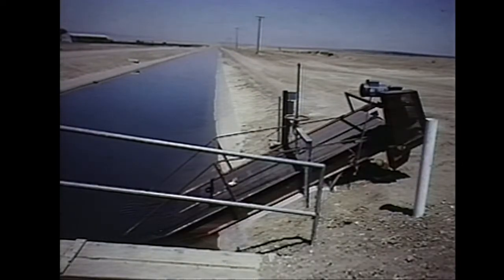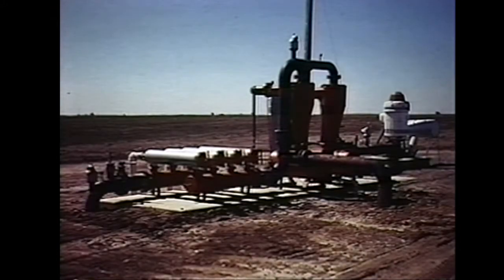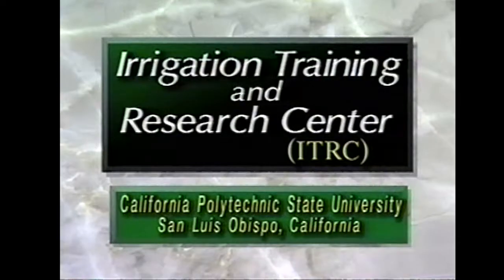In summary, there is a wide variety of filter designs available. Most filters are designed for a limited application. Others, such as media tanks, can provide filtration for a wide range of conditions, but only if they are sized, adjusted, and maintained properly. For more detailed information, the Cal Poly ITRC has published a book on drip and microirrigation. It has also produced another video on media filters.